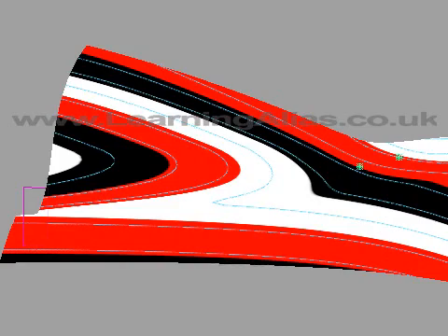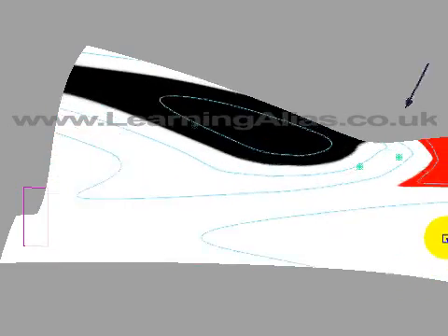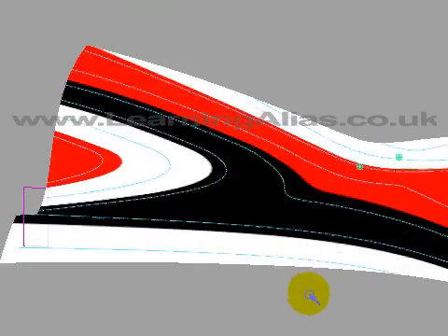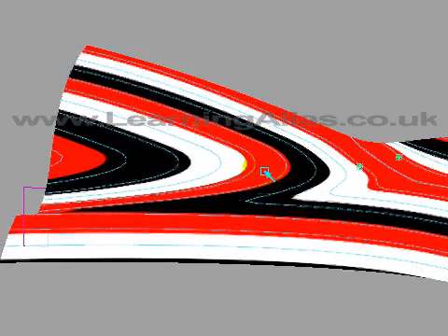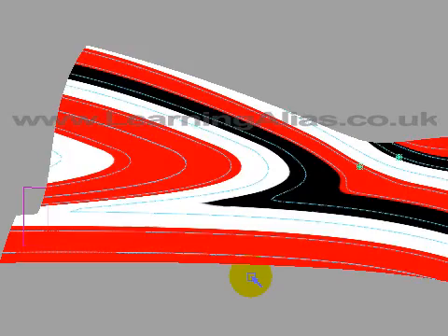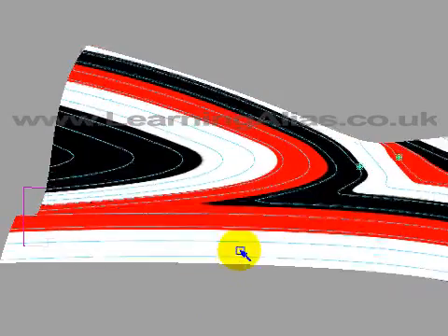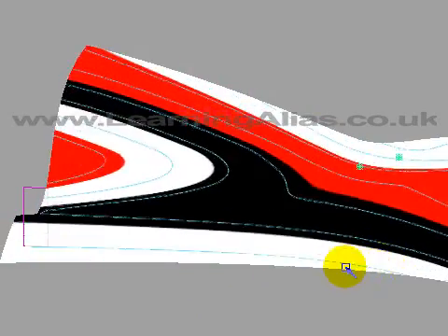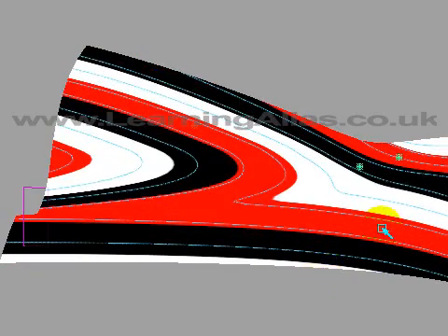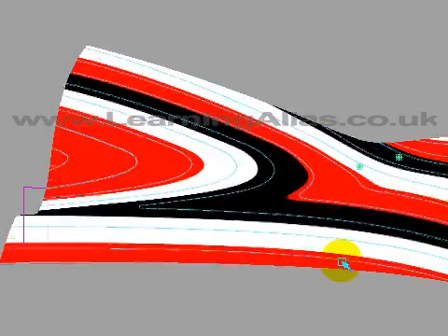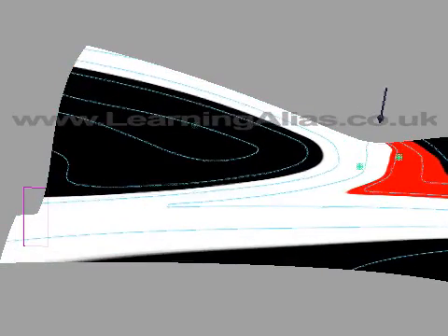And then finally, to close the tutorial, I'm using the ISO shader here and dynamically assessing the model. You can see that I'm looking here at the G3 continuity, and I'm looking also for defects. And if I'm going to be honest, I can point out here that there's something to investigate there, perhaps a bit of a flat spot in the model, but generally speaking I'm very happy with those surfaces.